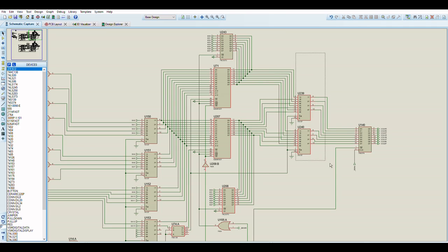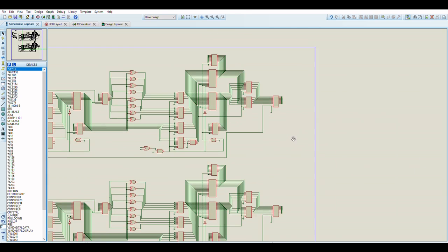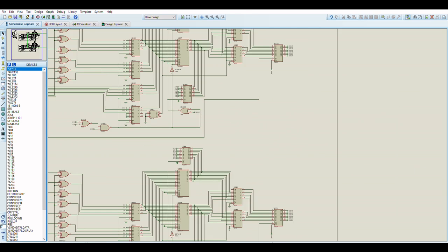It finally then latches the output 8-bit pixel here for the tile that is currently being rendered on the off cycle. And it goes to the output here. And what it means is that then this or this alternate being active for outputting the tile pixel for the mode 7 layer.